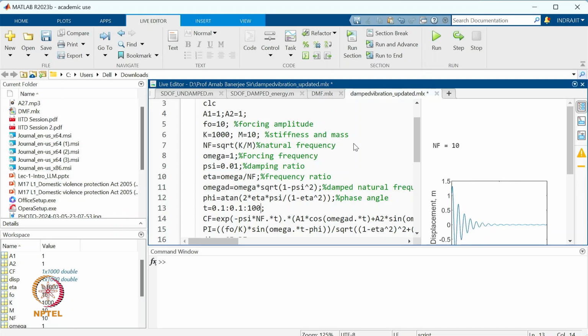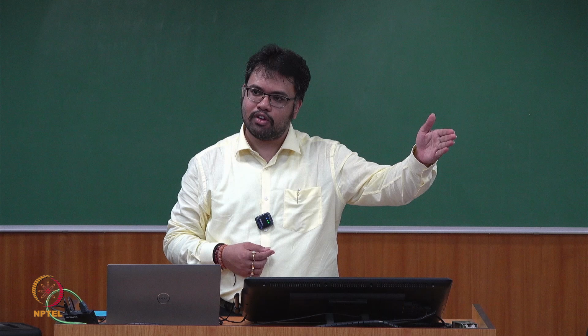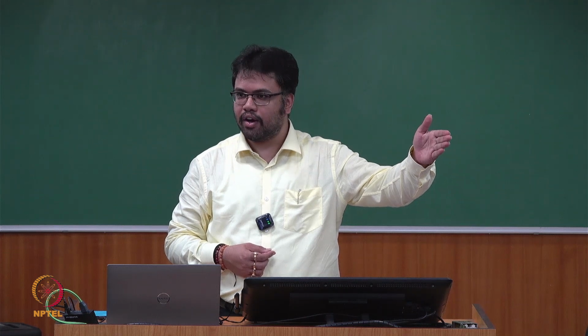So you see, it's almost like a pre-vibration type thing, that it gets decayed and you have very little amplification, because your excitation frequency is very low. You are almost at the starting phase of the dynamic amplification factor curve.